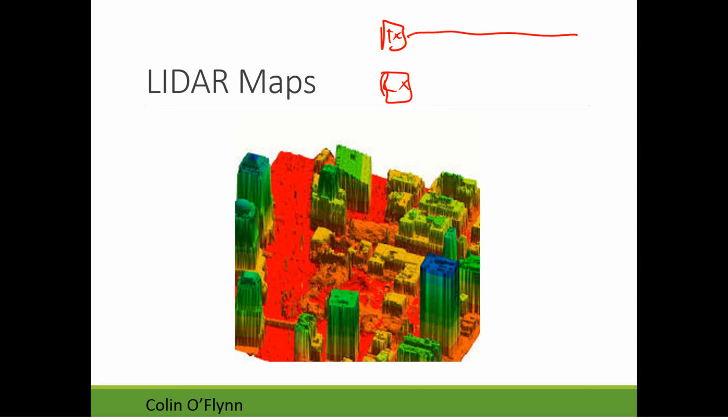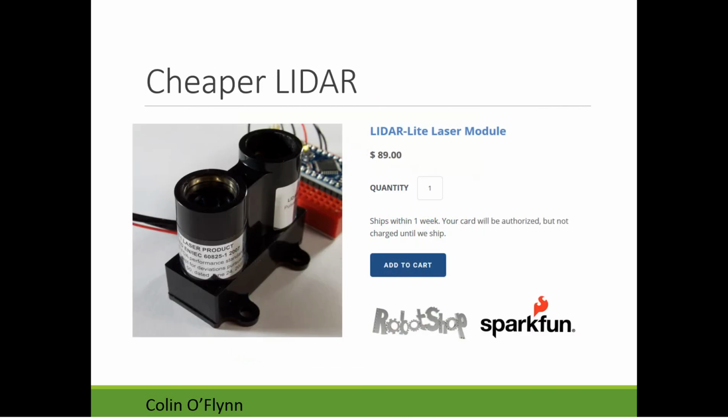And that received echo is only going to come if this object is right at position A. If it's just above it or just below it, there'll be no echo. So the main advantage of LiDAR is that you get a much more accurate picture. Because of that, the LiDAR system is almost always scanned, so you'll never see it just pointed randomly at one thing. Normally it's scanned to give you a map like this.